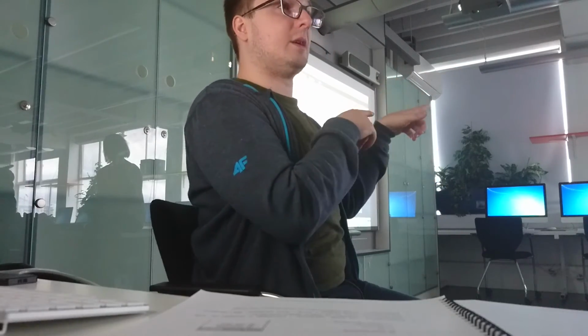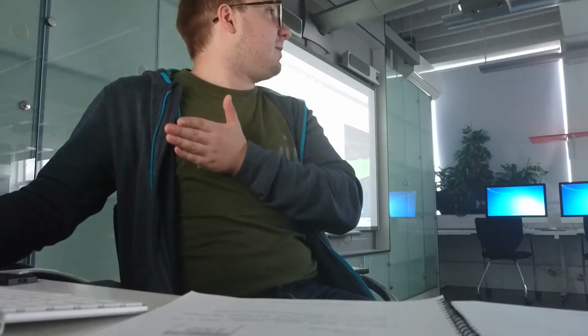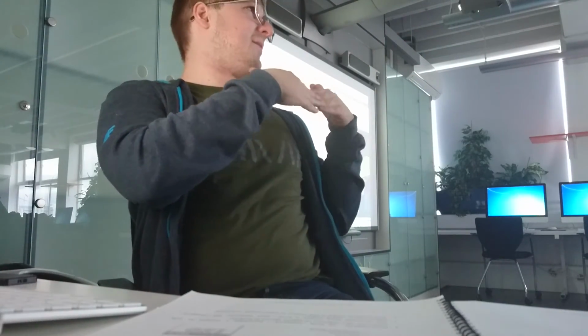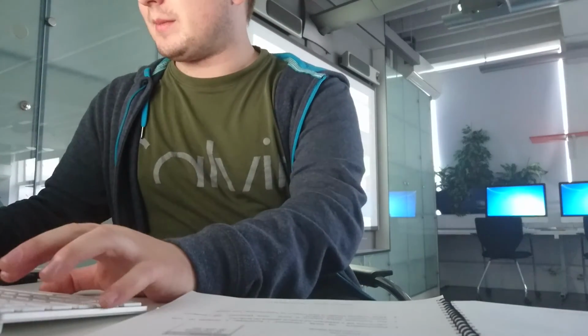I think her question is: there is a green and red, but what's the problem? Here you don't know what the problem is, but I'm telling you this is HVAC. So you can find out at the very beginning what you're looking for. Here you have to interpret. Basically we run file against file. We put a clearance tolerance of 1 millimeter, so it will be looking for basically every single clash. I'll show in a second.